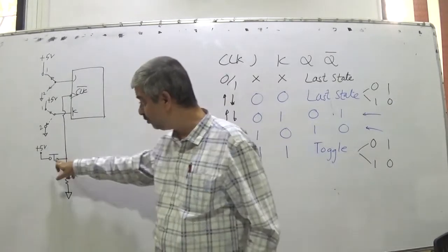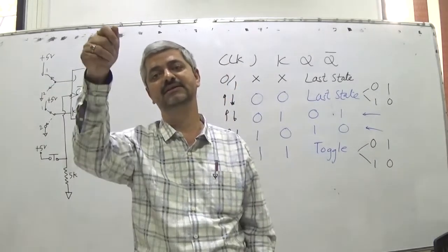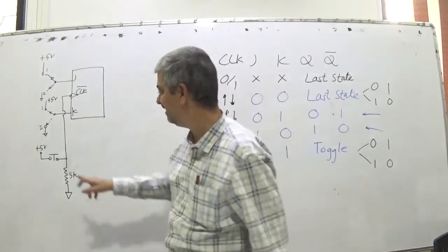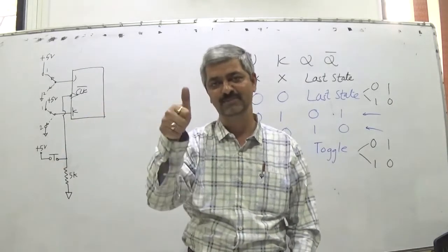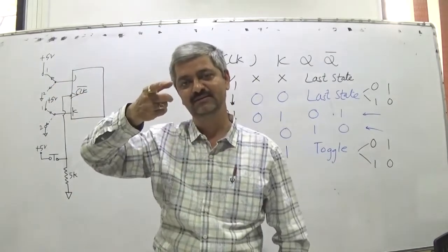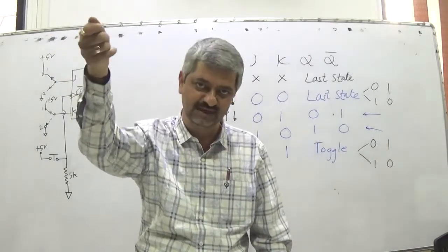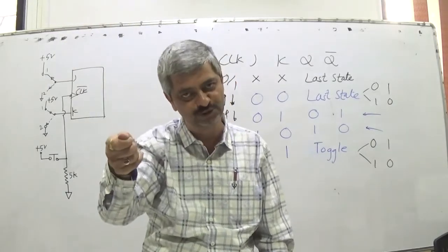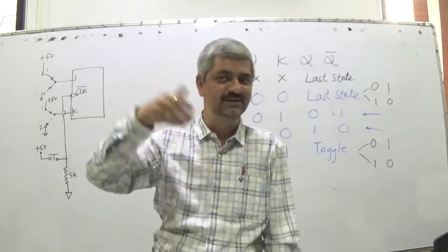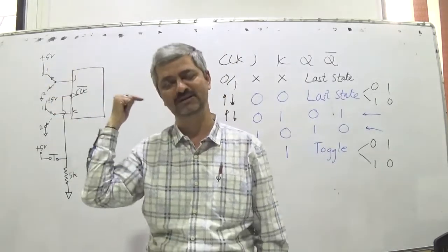It is a push button switch, and this is a one pole two-way switch. Means this switch is having two positions, just like staircase wiring, and this is just like a bell. So the switch is a doorbell. This switch can remain in any position. If you put it at one position, it will remain at one position. If you put it at two position, it will remain two position continuously, unless you change it again. Whereas this switch is like a doorbell switch. If you don't do anything, it will remain open. You have to press to close, and once you release again it opens.